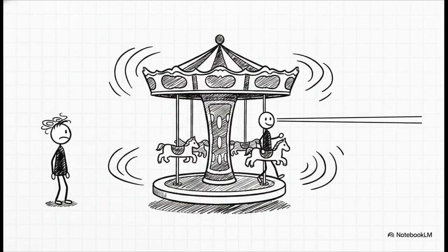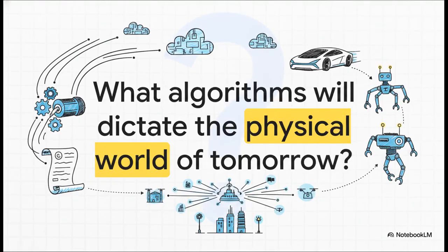Think of it like this. If you're standing next to a spinning merry-go-round, the horses are constantly zooming past you in this chaotic wave. But if you step onto the merry-go-round and spin with it, the horses suddenly appear totally stationary relative to you. The Park transform steps onto the rotating magnetic field of the motor, and suddenly those chaotic AC waves become steady, easy-to-control DC values, the direct component for flux and the quadrature component for torque. Mind-blowing, right? It is truly amazing to think about.